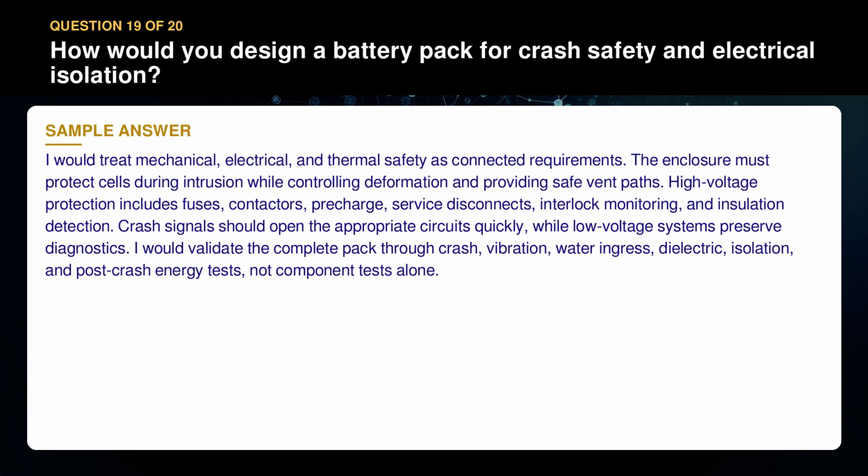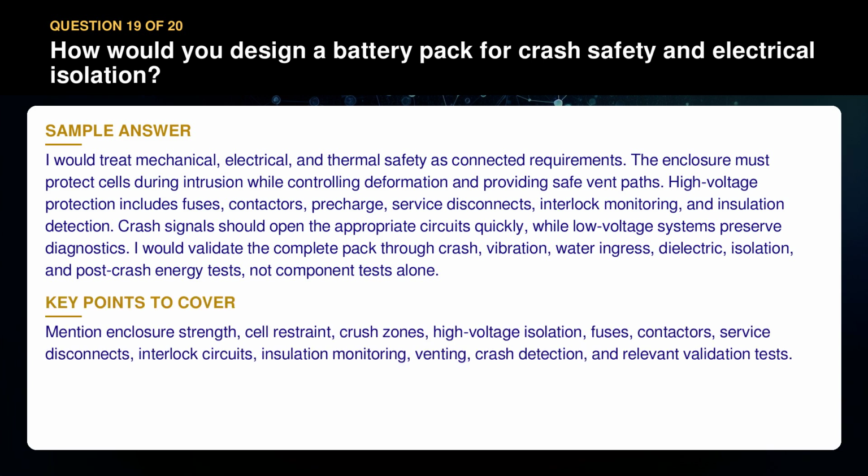I would validate the complete pack through crash, vibration, water ingress, dielectric, isolation, and post-crash energy tests, not component tests alone. Mention enclosure strength, cell restraint, crush zones, high-voltage isolation, fuses, contactors, service disconnects, interlock circuits, insulation monitoring, venting, crash detection, and relevant validation tests.